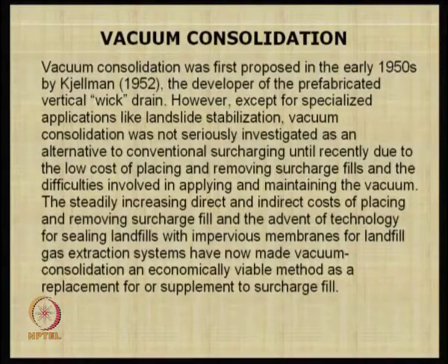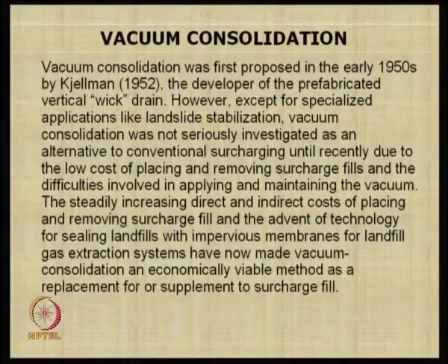Another important point I would like to indicate here is that there is another technique called vacuum consolidation. Vacuum consolidation is something people proposed in 1952. The advantage of the vacuum is that you try to remove all the air present. Even in a saturated soil, if you just create a vacuum, there is an accelerated drainage that takes place. They were using it in some applications like landslides.